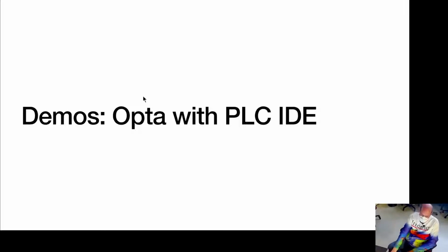Right, I think I was misunderstanding. If your PLC can do the PWM control of it, you wouldn't need the relay. You would just do it with the controller. If you want a PWM output, you need the correct kind of output for your PLC, like a transistor or something. And I'll talk later about how to get that.